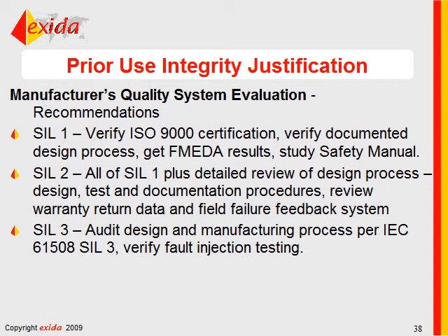For SIL 2, I would do all of the SIL 1 activities, plus a detailed review of the design process. How do they design equipment? How do they test? What documents are produced? How do these compare with good, accepted engineering procedures?